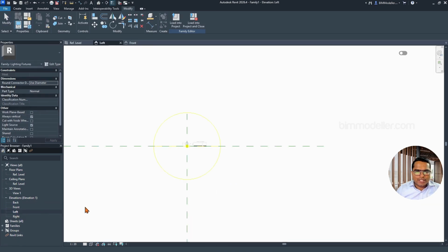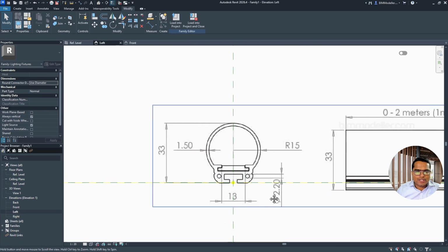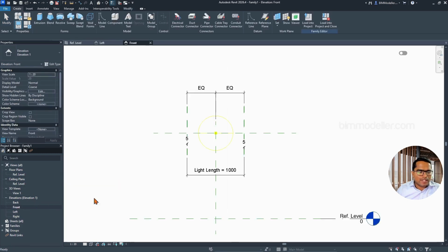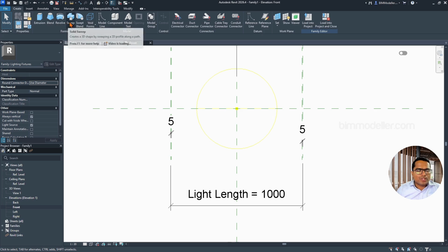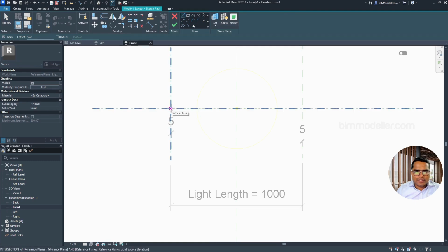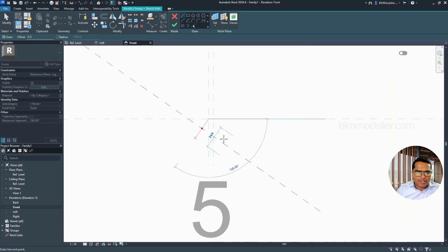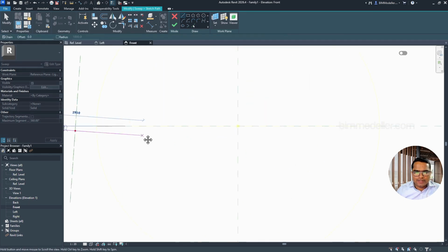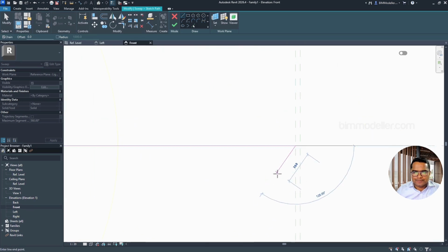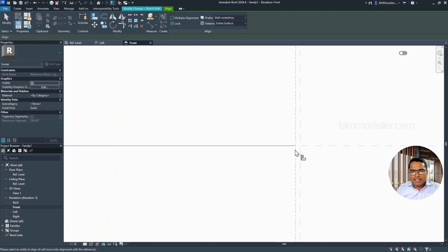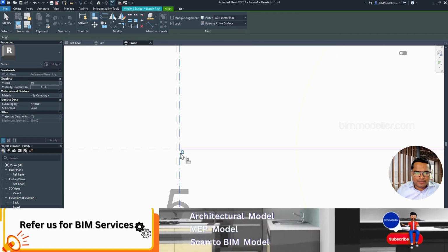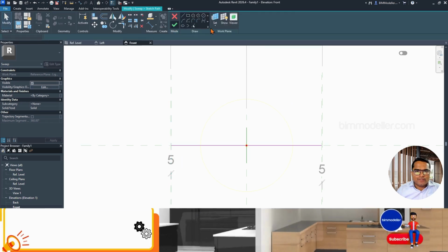We can go back to the left side and draw the sketch as we needed. Meanwhile, we can draw the front view path as well. We're going to draw the sweep and sketch the path. It's going to start at this place. We can make sure that the end is here on the right side. Use the align command AL, lock the edges. And now we can finish and edit it.